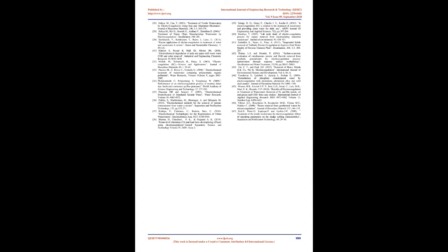For conclusion. This review was focused on the electrocoagulation method to treat industrial wastewater by studying the mechanism, chemical reactions on the electrodes used, and the affected parameters such as pH, current density, electrode material, time, electrical energy and electrode consumption, applied voltage, etc. It was found that the electrocoagulation technique is an effective treatment for the removal of heavy metals from industrial wastewater as it is economical and has higher removal efficiency than other conventional treatment methods. This process requires simple equipment and easy operation.